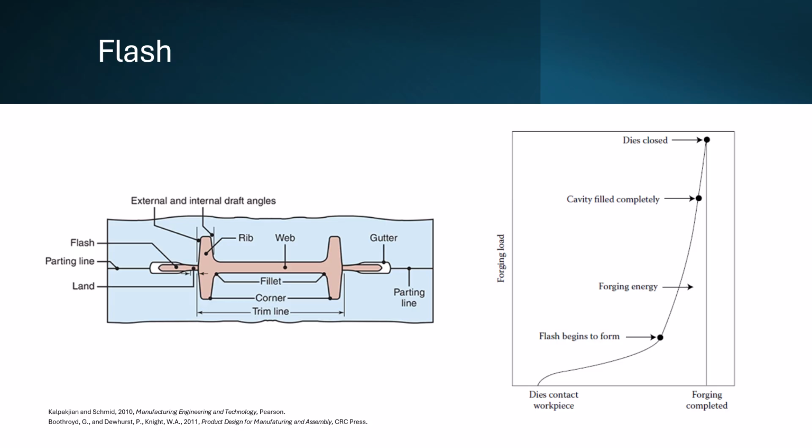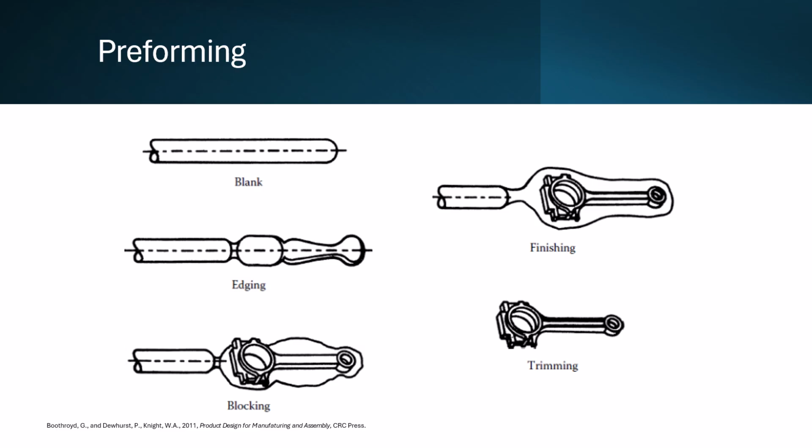The final step during forging is removal of the flash, webbing, and oxidation. Machining can be used for all three, but is a more expensive process. Alternatively, a trimming die can be used to shear off flash and pierce holes for webs. This is cheaper than machining and is done while the part is still hot.